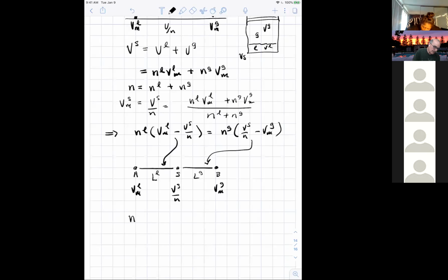And we get NL times the length of that L, liquid phase, plus NG times the length of that gas phase, right? Or, I'm sorry, it's gas, not solid. I just can't read my own writing. NG over NL equals the inverse of the lengths. This is known as the lever rule.